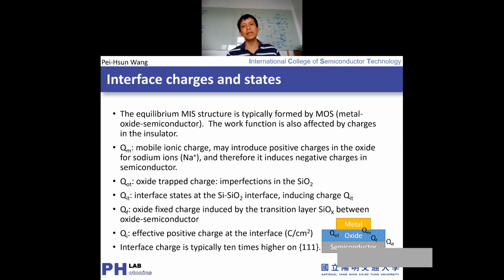When you design for high power, we typically use the SVT, like the standard cell. But if you want to work with really low leakage current or low operation voltage, we change the metal composition. So instead of using different doping, we change the metal composition, and try to avoid any unwanted defects like interface traps and oxide traps.